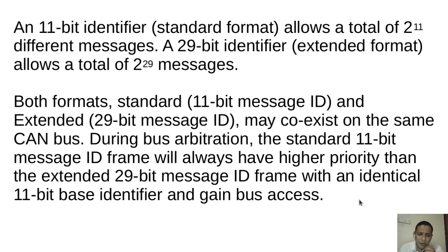We have seen the priority arbitration in the CAN structure. So CAN extended format as well as CAN standard format may occur in the same CAN network, but we decide whether to use standard or extended based on the IDE bit.